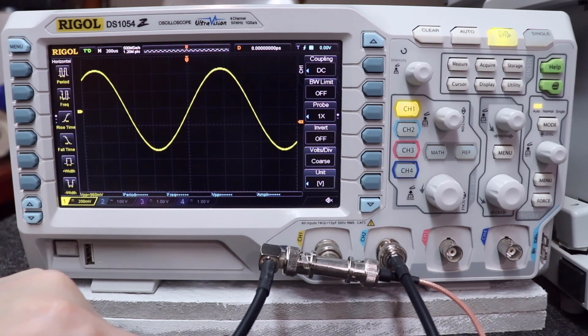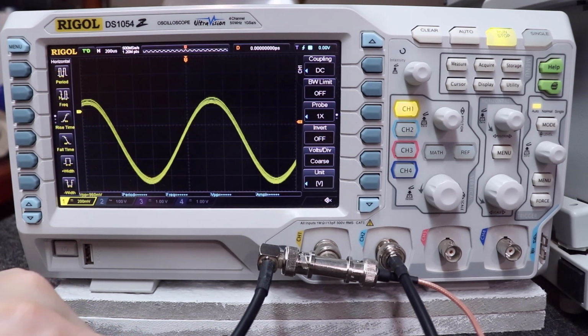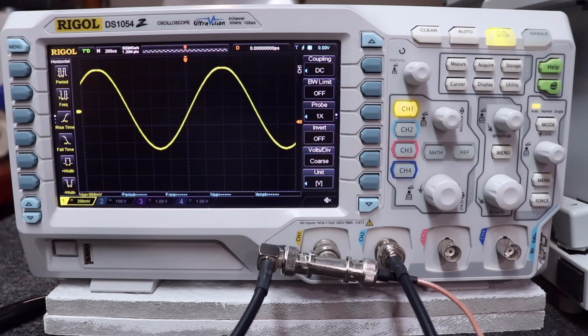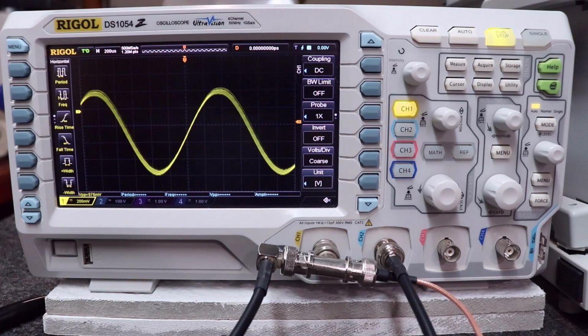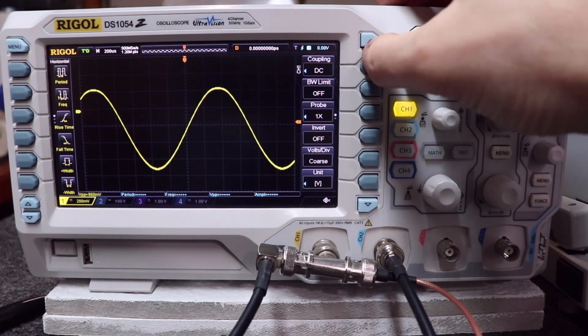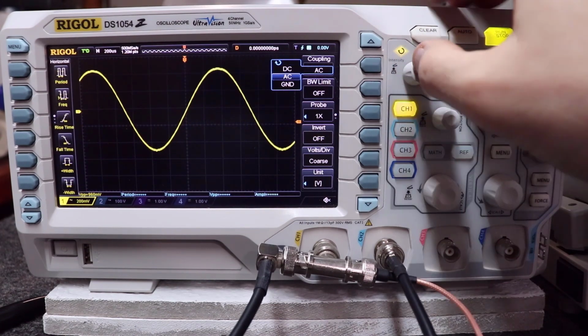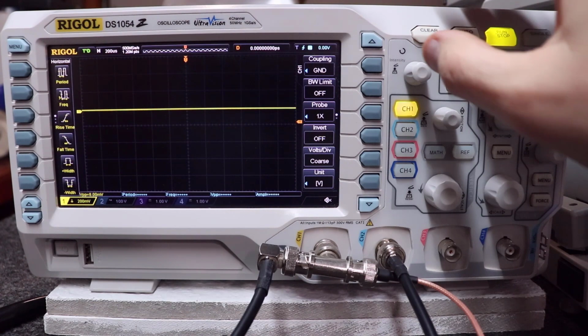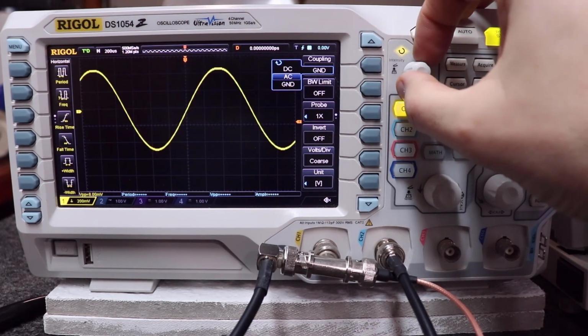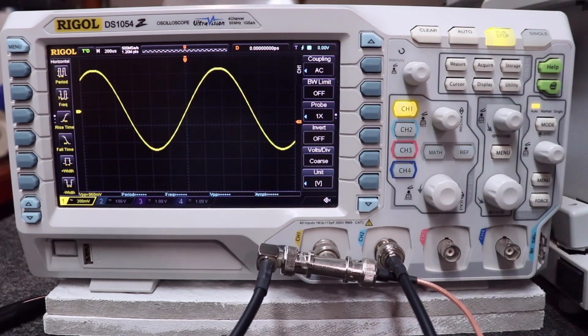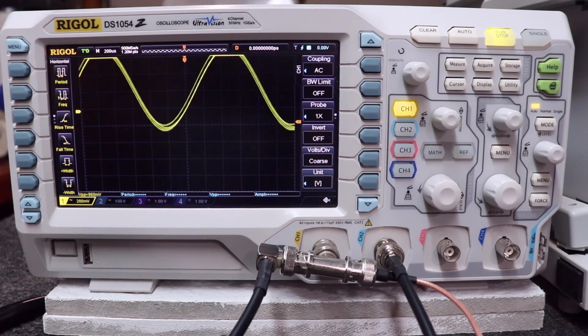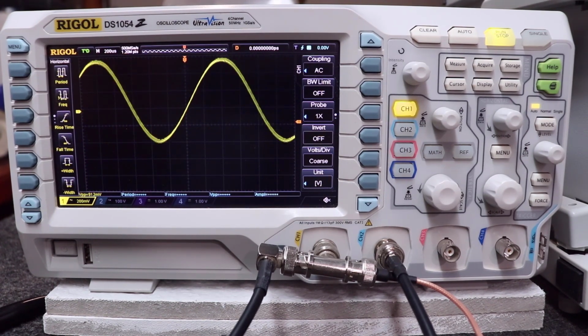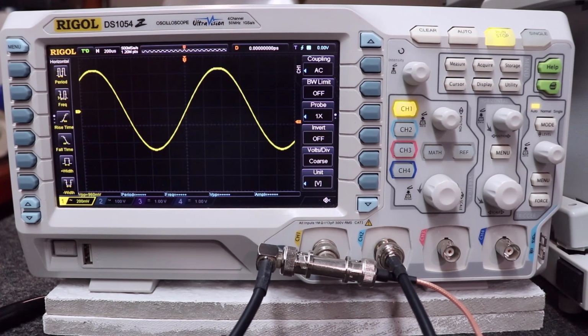So if I have some DC offset on this unit, look at that. It varies the signal, right, as I change the DC offset. If I come over here and put this on AC coupling right here, click on it. Whoops, clicked on ground by accident. AC couple it, right? Now I am varying my DC offset, but what does it do? It always settles back down and it cuts out that AC component.